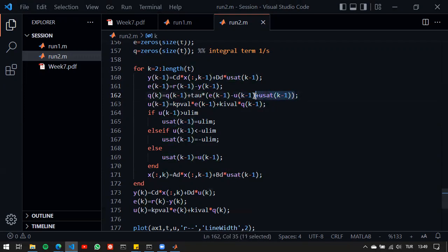Let's just take this away and put back the actual value. So in this case, for example, if we calculate 20 here instead of the control signal and apply 0.7, we are subtracting basically 20 and adding 0.7. So we're correcting the sum during the saturation here.